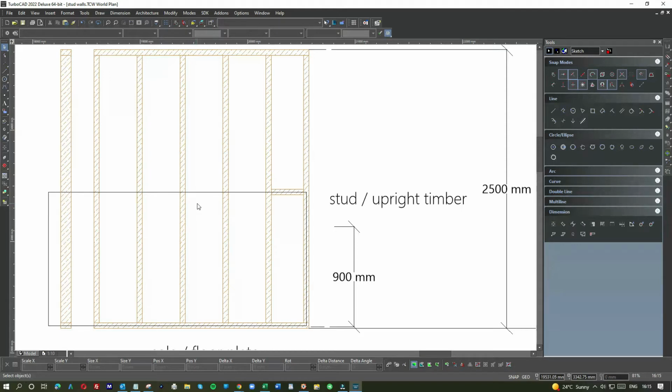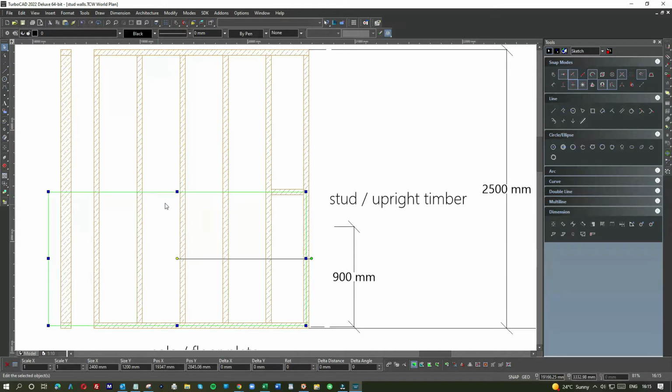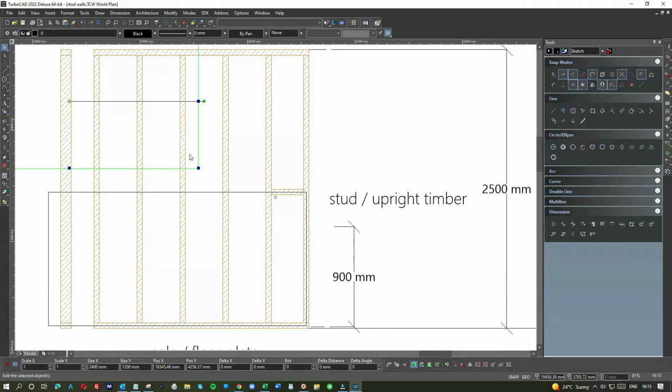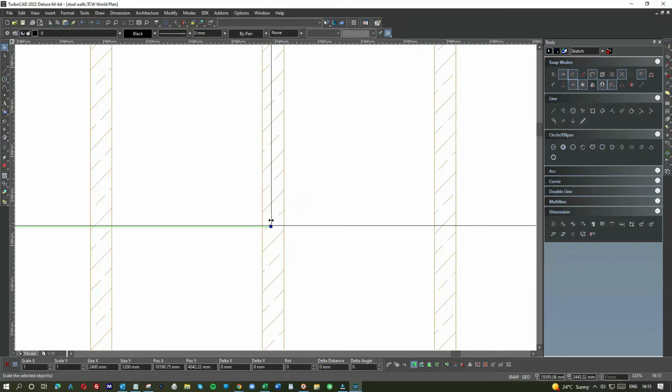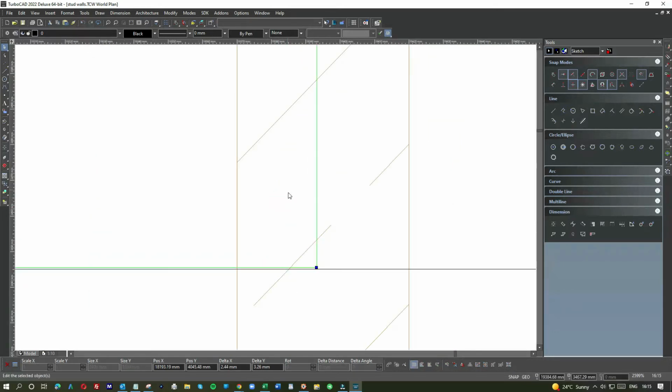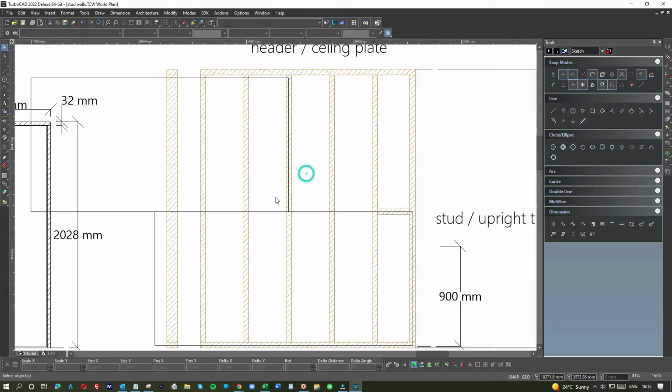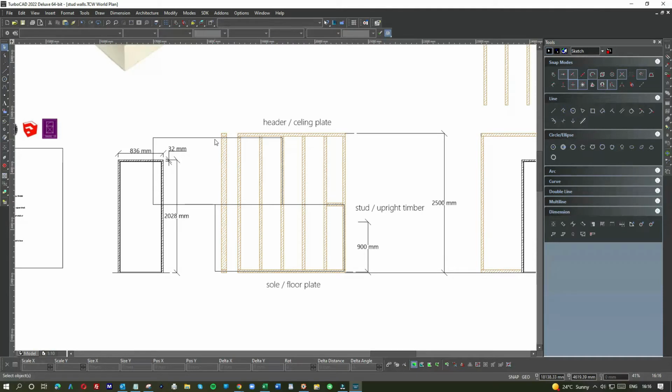Then the next sheet of plasterboard, let's assume you were doing 8x4s. The next sheet of plasterboard you would stagger. Now what I mean by that is that you would start the board, say, similar to that. In other words, you do a sheet here, and you wouldn't put it directly on top of the one below. It's good practice to stagger the plasterboard. You put the plasterboard on like a bricklayer lays bricks.